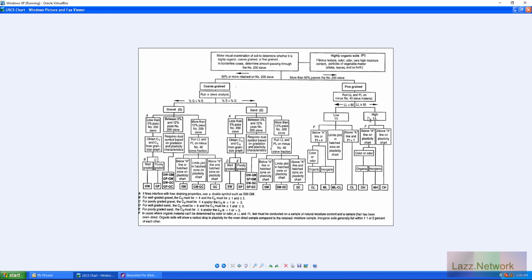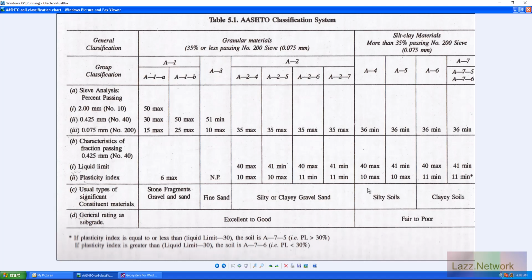Yeah, because this cares about where your liquid limit is going to be. This one doesn't care about your liquid limit; all it cares about is your plastic index. Your plastic limit is just there to help determine your plastic index. Because remember, your liquid limit minus your plastic limit gets you your plastic index. So as people will say, LL minus PL equals PI, if you're in any of those engineering classes with soil mechanics and whatnot.